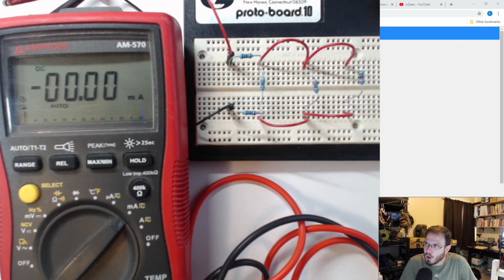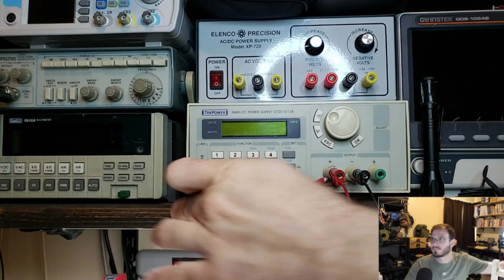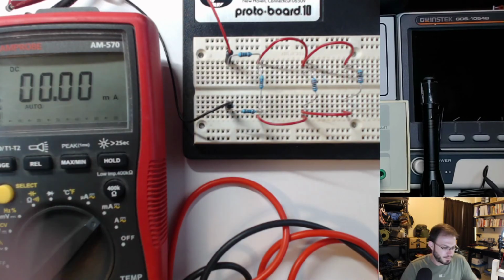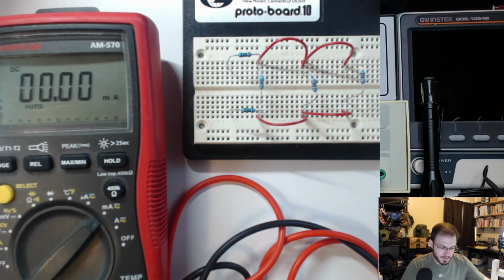So I'm going to go ahead and finish today's session off with that. We have current for RT. Oh, do we use the DMM to calculate the total? Sure. Let's go ahead and measure the resistance for the whole circuit. I'm going to turn off my power supply. It is now off. I'm going to go back to my whiteboard and disconnect the power leads from there.